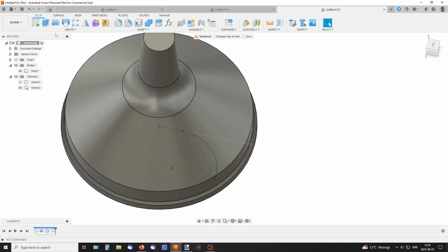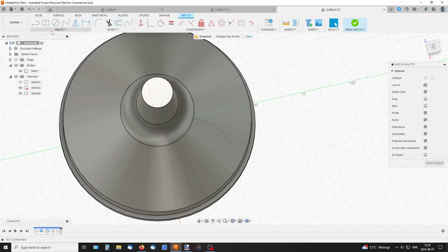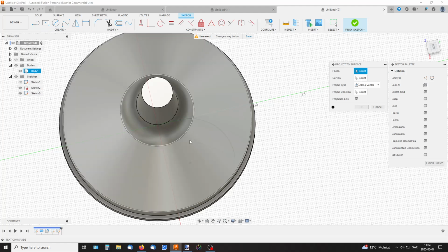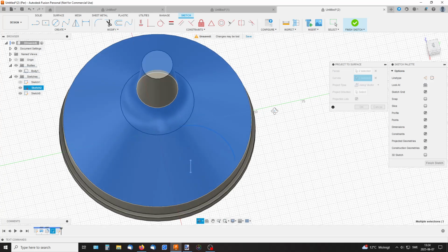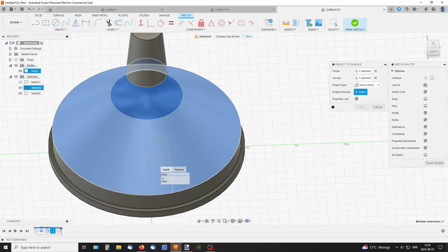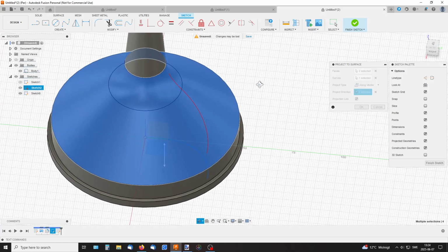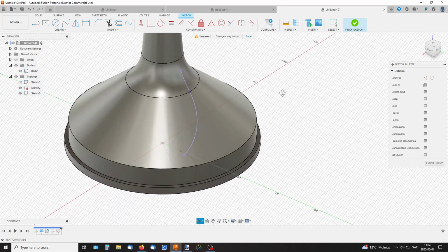So of course we could try, if you make a new sketch, we could try to project the surface up here, and this is the curve. And we also need to project direction. So I long click and select that top face. And there we got a preview of our path.